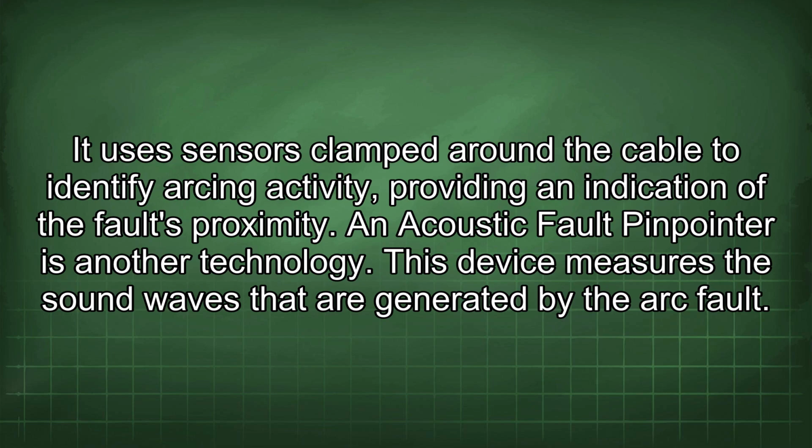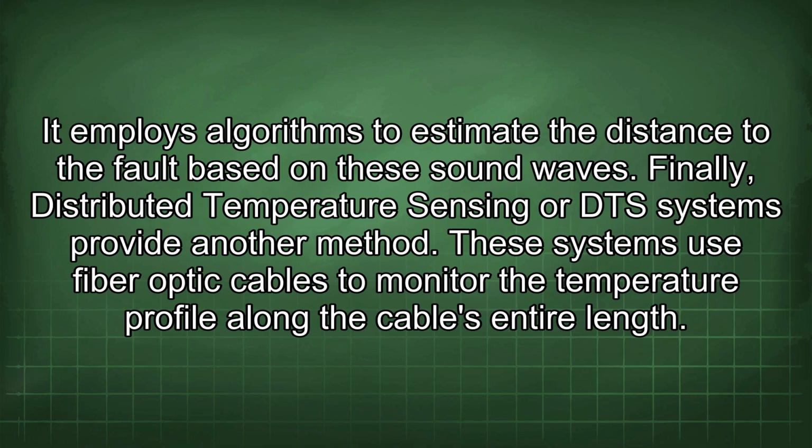An acoustic fault pinpointer is another technology. This device measures the sound waves that are generated by the arc fault. It employs algorithms to estimate the distance to the fault based on these sound waves.